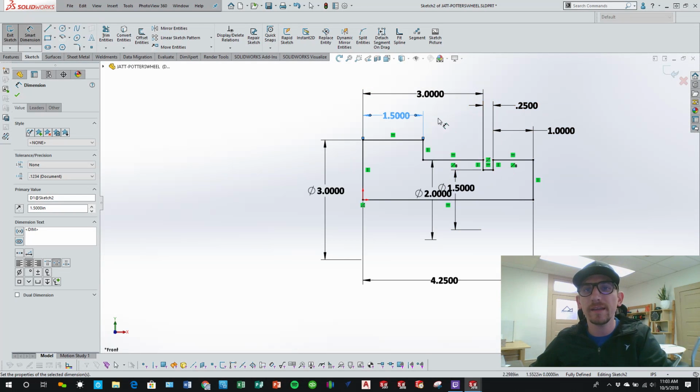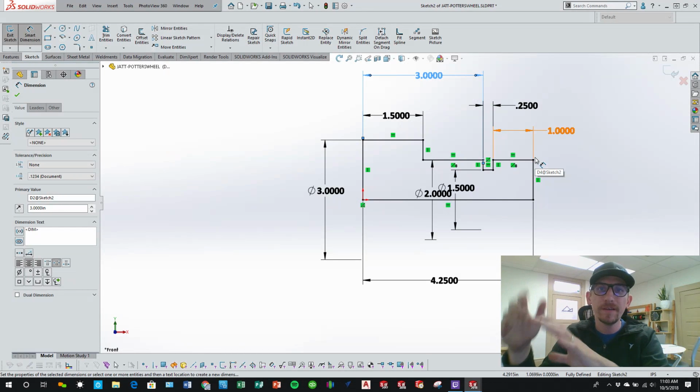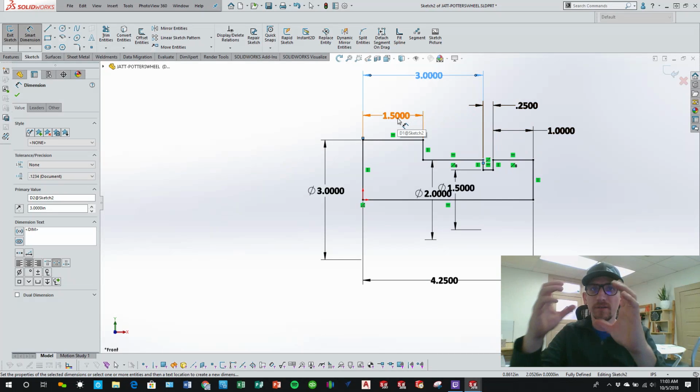The reason is this 3-inch dimension. I gave it a rule saying, look, I want my groove here for my retaining ring to always be 3 inches off from my flat face here. So that makes it so my groove and also my extended excess material on the end does not get affected by the dimension of whatever hole my shaft fits into.